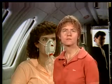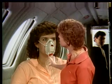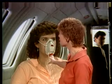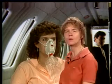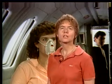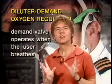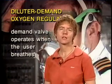Now, how do you control the amount of oxygen that's going to be delivered to a mask like this? A calibrated orifice in the system. In other words, where that mask plugs into the aircraft oxygen system, there will be a calibrated orifice, a hole of a certain size, and that controls the volume of oxygen that will be delivered to that mask. Now, the type of mask that the crew would typically use, and particularly in an aircraft that is normally pressurized, is a diluter demand oxygen regulator system.